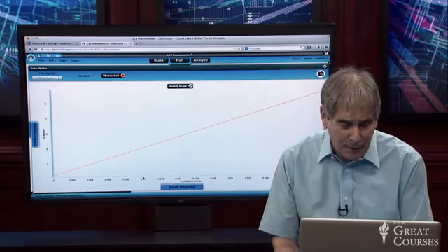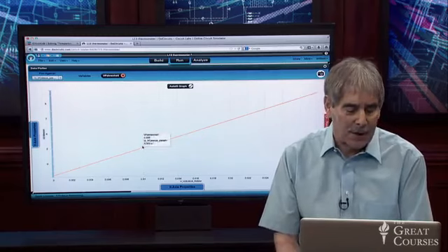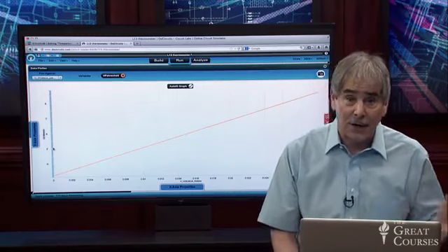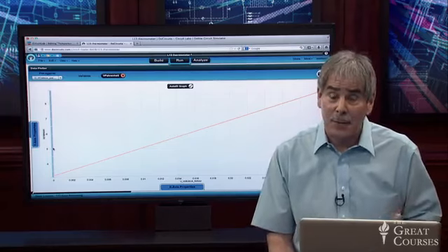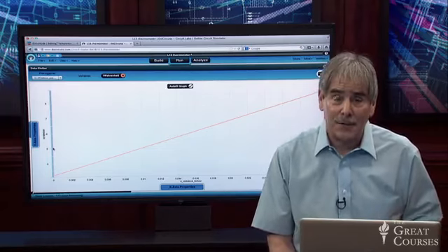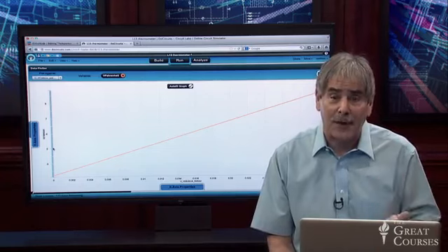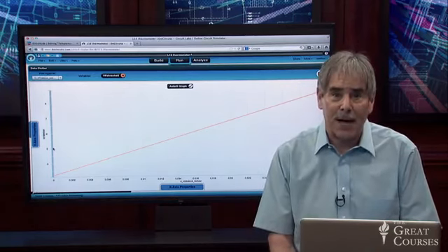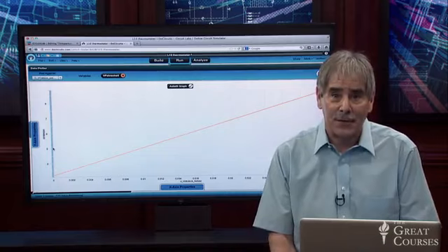For example, 0.01 volts, 10 millivolts corresponds to 5 volts at the output, so 10 degrees Celsius corresponds to 50 degrees Fahrenheit. That was a pretty sophisticated assignment, to work that out and get the summing amplifier to sum in the 32-degree offset. Not trivial. If you did that, pat yourself on the back for doing a really sophisticated circuit.